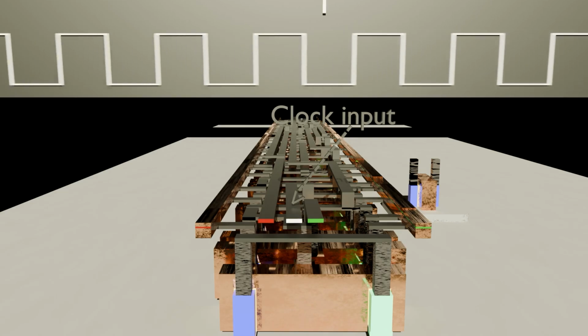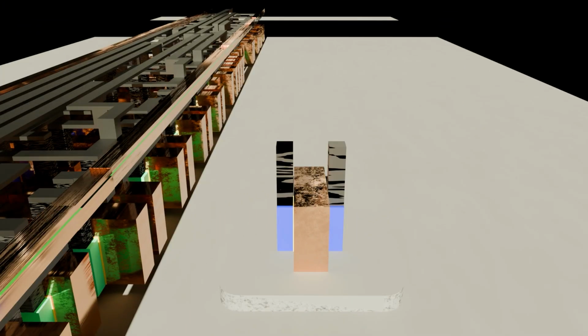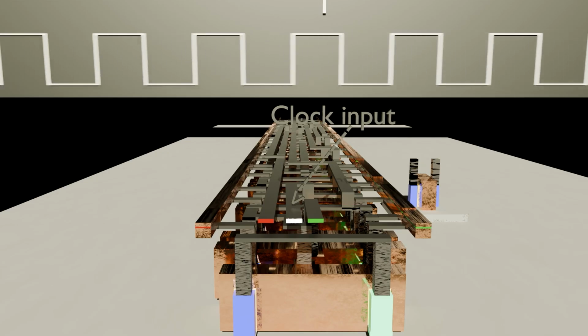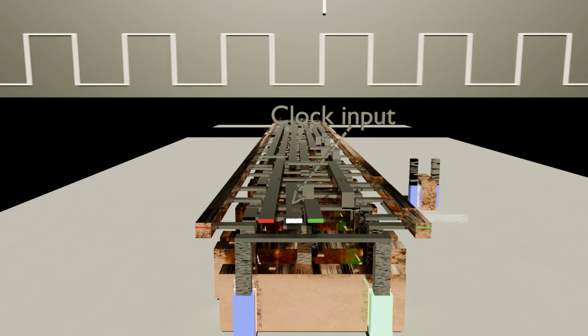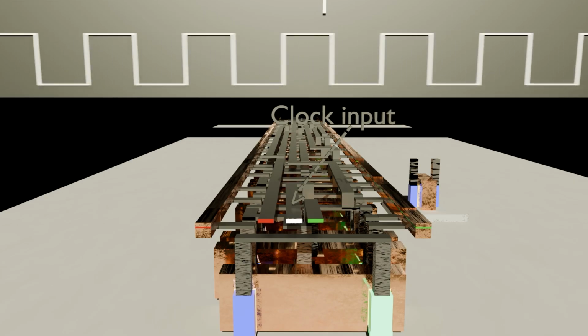here. And this leads us to combinational versus sequential logic. Combinational logic is just input to output logic. Sequential is dependent on its stored state. Like this D flip-flop here, memory is just logic that feeds back into itself. This flip-flop stores 1 bit and keeps on updating it each clock cycle.